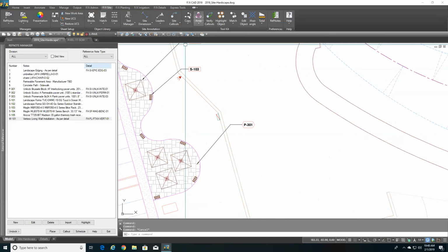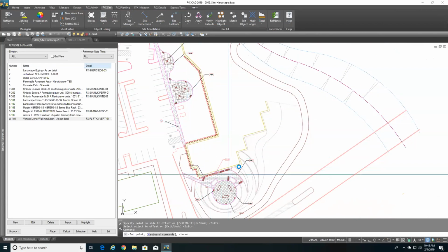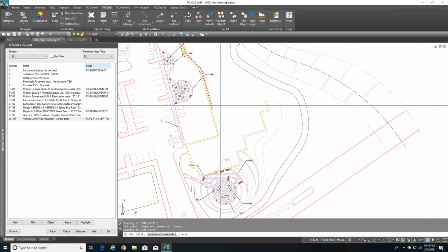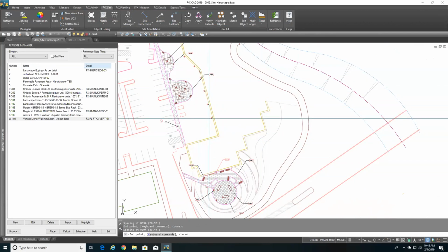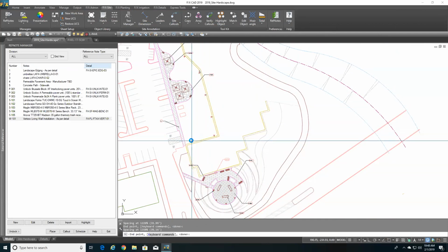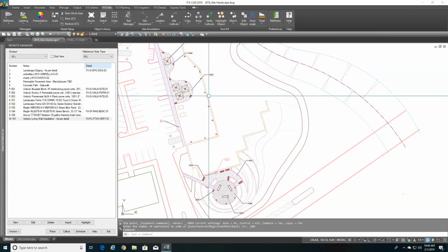So what I'm going to do is find that copy along line tool again, pick the source object, pick that polyline, and just start dragging things along this wall here. So again, it's just going to pick fixtures, place them and duplicate them along this line as far as you specify, really. So I'm just going to use some of my short keyboard command tools again. Probably get a little less spacing, do something like that. And I instantly have equally spaced fixtures placed on this wall over here.